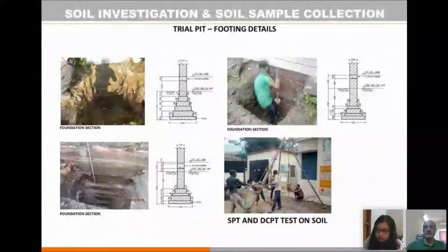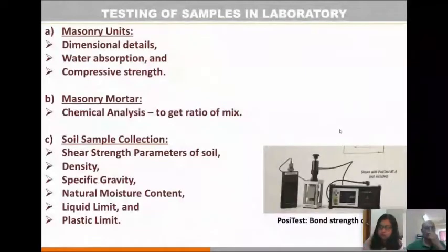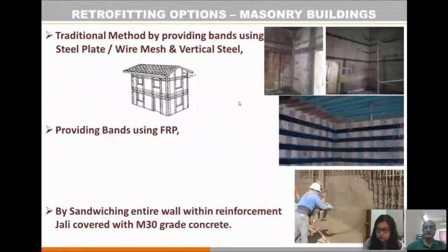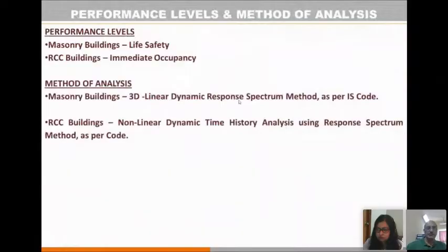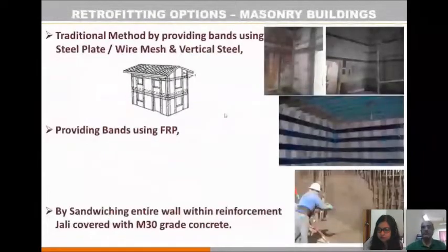This is one of the pictures which shows the investigation of the soil and existing foundations by conducting trial pits. Based on the different tests, you can delineate the deficient members and decide the appropriate retrofitting strategy. There are various retrofitting strategies available separately for masonry buildings and for RCC buildings.